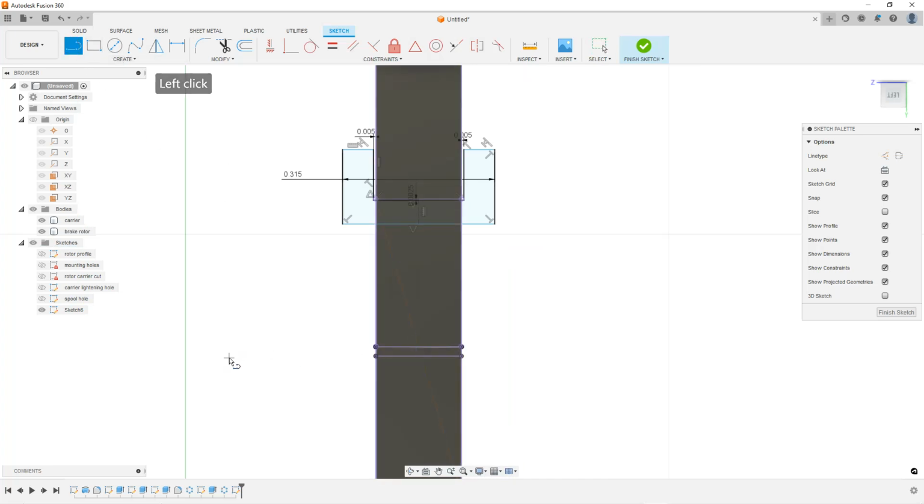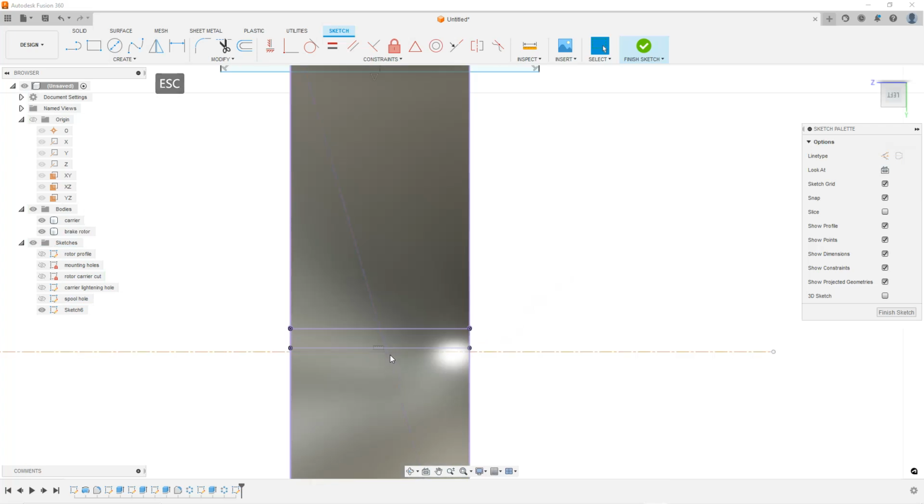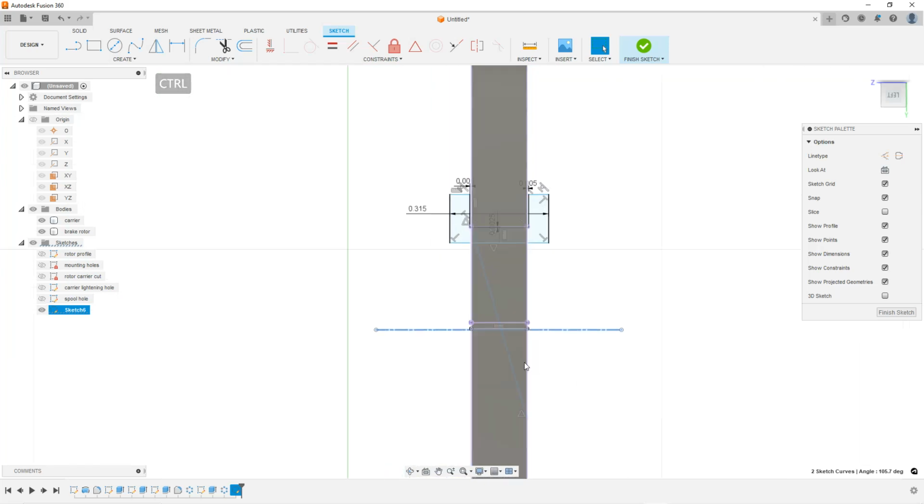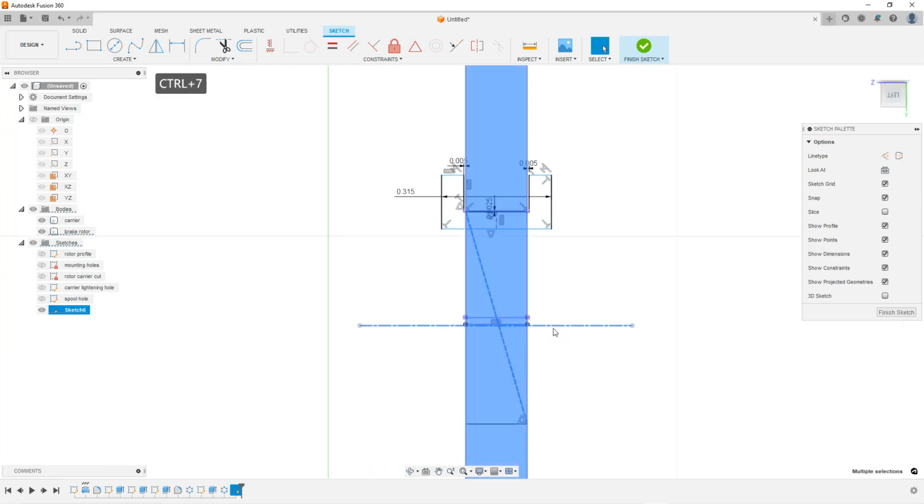And I'm going to draw a center line because I'm going to revolve this spool. Okay, and I'm going to do a midpoint. So this line extends from kind of one edge of the hole to the other edge of the hole diagonally, so I know that the midpoint of this line is in the middle of this hole in both directions.